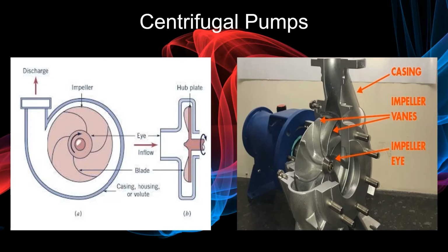It comes with our patented impeller and casing. The pump functions by the impeller rotating and sucking fluid through the eye of the casing so that the fluid flows radially outward. The rotating blades of the impeller add energy to the fluid, resulting in an increase in pressure and velocity as the fluid flows towards the periphery of the blade, where it is discharged into the volute casing. Once in the volute casing, the velocity of the fluid is reduced, corresponding to another increase in fluid pressure, and a uniform velocity distribution is discharged out of the pump.